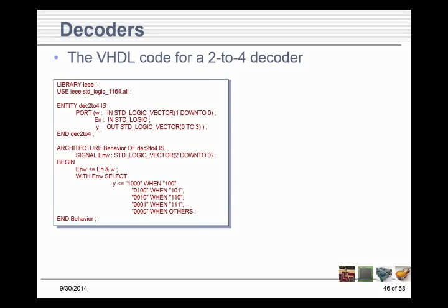This really is bit 0. I'm telling it here when the enable is 1 and W, the select, is choosing 0, make line 0 go high. Let the other ones be low. Here I'm saying when enable is 1 and I'm selecting 1, let line 1 go high. All the others have got to go low. When enable is 1 and I select line 2, let line 2 go low. But that looks weird because it's backwards from the other ones. Okay?